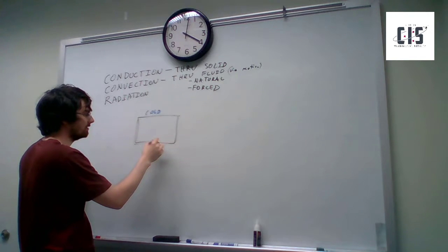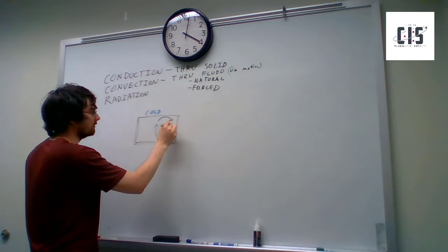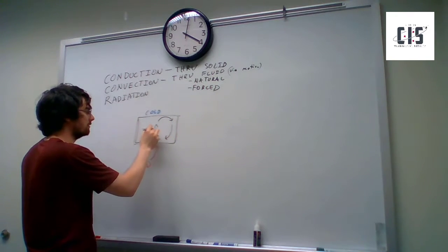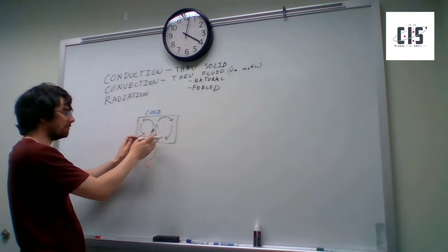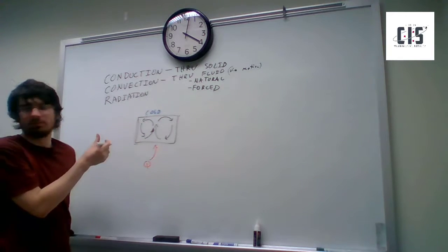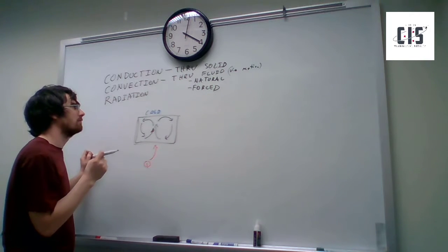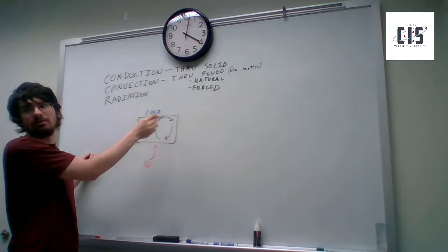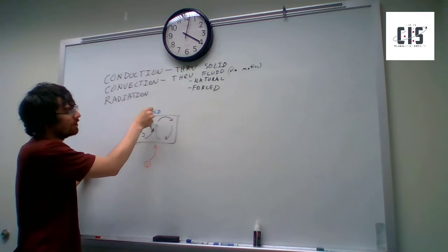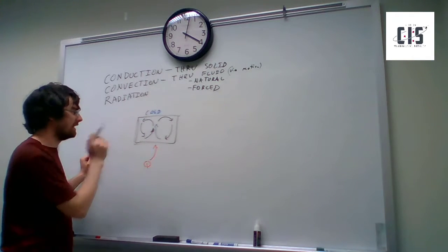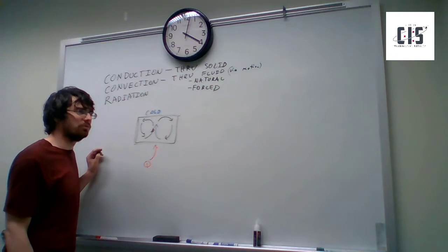And this tends to cause convection currents, where the fluid tends to move up and around. So it heats up and rises, and then it cools down and drops, and usually makes kind of currents of sorts. It could be in this direction, it could be a different direction, but the densities of the fluid are what's causing it to move. Because when it heats up, the density drops, making it rise. When it cools down, the density rises, making it sink. So that's natural convection.